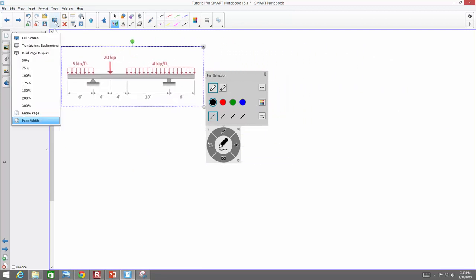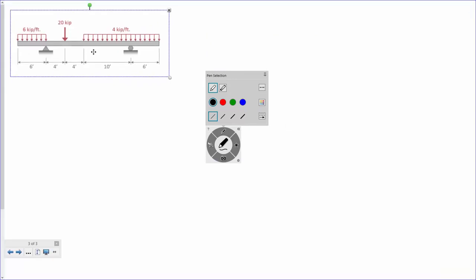Real quick before we get on, you said we're not going to do any statically indeterminate, but just so I remember, statically indeterminate would be if you replace the roller with another pin. Yeah. Now, not technically for this problem because all the loads are still vertical, but what if I put another roller on it? That would be statically indeterminate because ultimately we would have more unknowns than we do equations of equilibrium. Remember that we only have 3 equations of equilibrium if we're dealing in 2 dimensions. We have sum of forces in the x direction, sum of forces in the y direction, and sum of moments. If I give you 4 unknowns, then that becomes indeterminate. Okay? That's a good question.